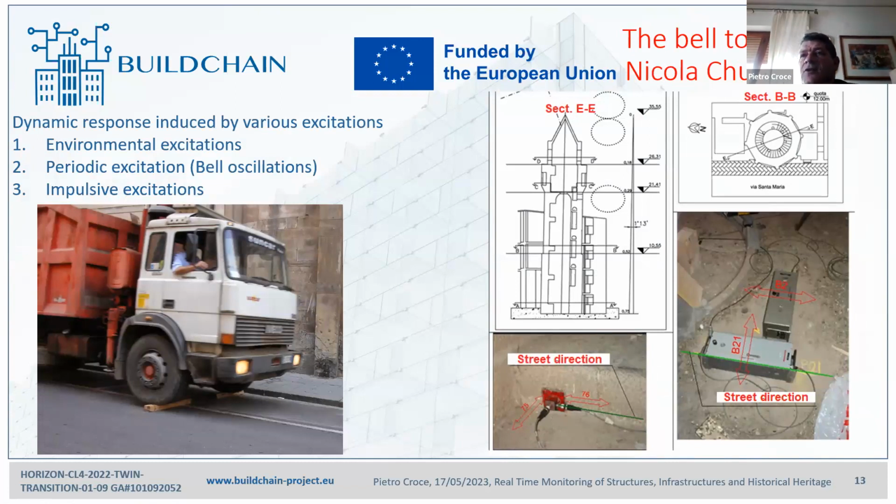As already said, often we use environmental excitation because vibrations induced by traffic or by wind are always present. In case of bell towers, often we use the bell oscillation as a source of excitation, so we have periodic excitation.